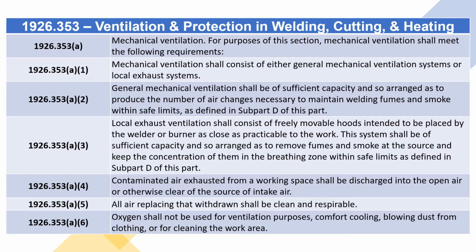A.3. Local exhaust ventilation shall consist of freely movable hoods intended to be placed by the welder or burner as close as practicable to the work. This system shall be of sufficient capacity and so arranged as to remove fumes and smoke at the source and keep the concentration of them in the breathing zone within safe limits as defined in subpart D of this part.